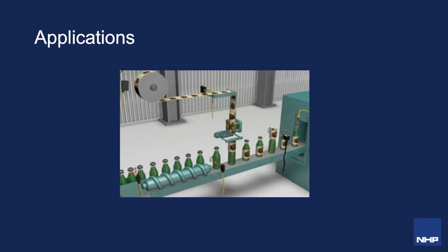But this again could also be done with a through beam sensor as before, and a capacitive sensor as before, but again, you might not need or want these types. It could also be done with a limit switch and with a whisker type actuator. It could detect every time the bottle passes. However, it's not as practical, especially as this would be a high speed and more frequent kind of application, and you would need to replace that regularly.